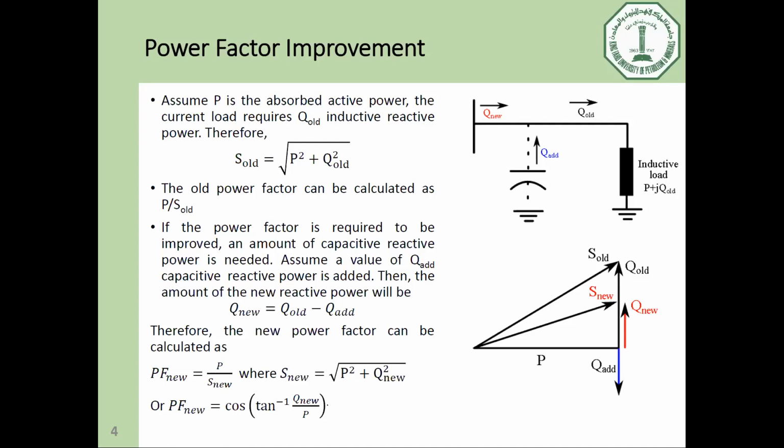In power stations, in order to regulate the voltage of the bus bar, we have to control the reactive power. This is only during transient. We will describe this in detail, God willing, in the synchronous machine: the voltage regulation, and how we can use reactive power in order to compensate the terminal voltage of the generator. And this is another issue.